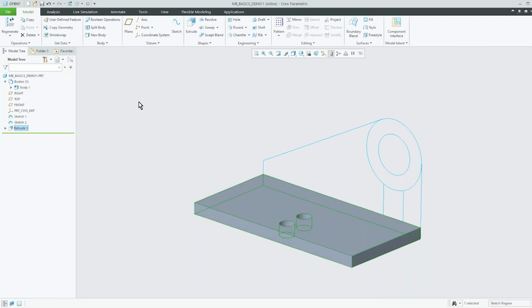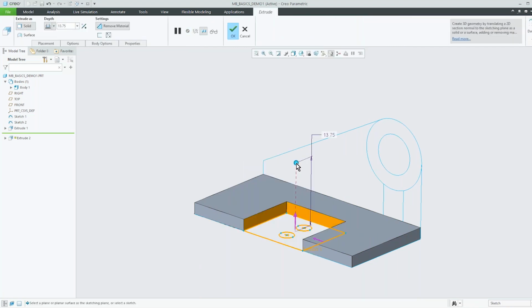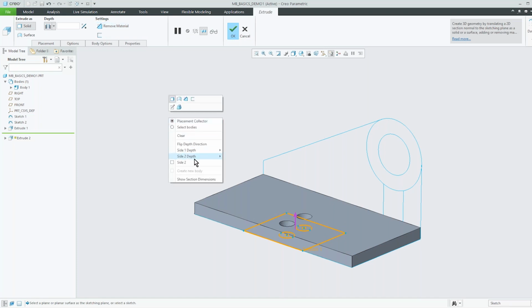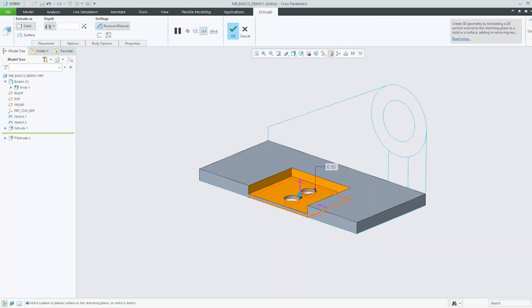And for me, if I look at it the way that Creo's always been, it's just a regular feature. It's an extrude feature, right? And we got some other sketches and things here. Let's go in and make some changes to body 1. So I'm going to take this guy and I'm going to say, let's extrude him up. I'll flip the directions. And we'll say, let's say through all. And we won't have it remove material. But now I'm going to say side 2, we'll say, let's kind of drag that up this way. And we will say remove material.